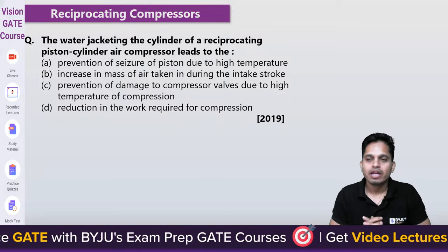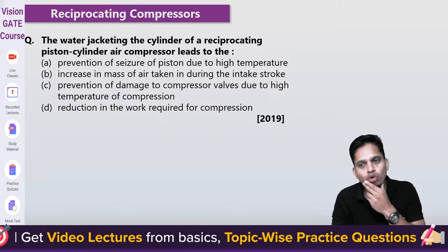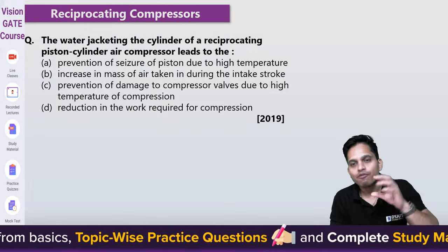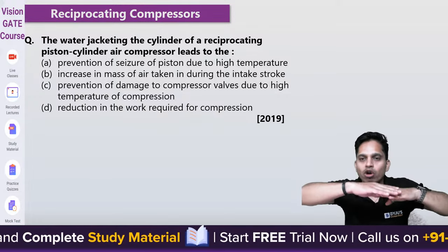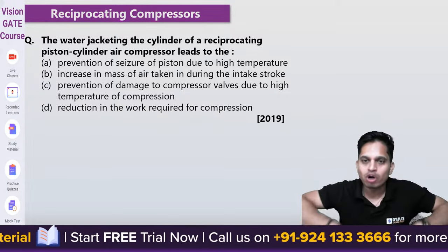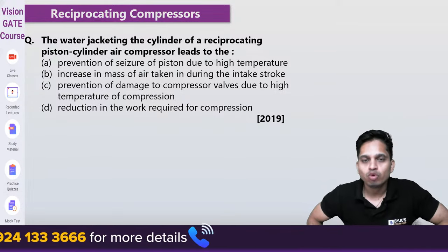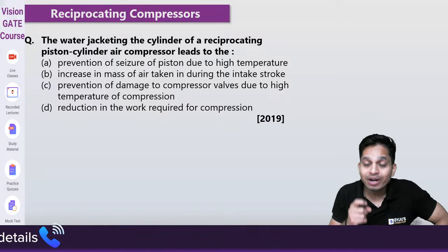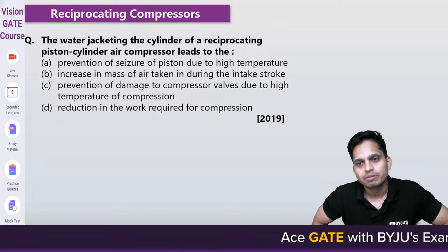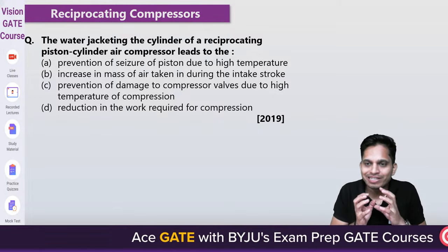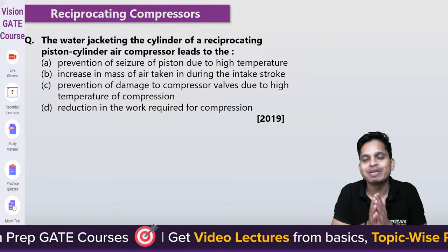No. Usually in a reciprocating compressor, valves are not inside, they are outside. They are plate type valves outside. This is spring controlled, so they will open and close outside only. They will not require space from inside. Then why do you give clearance? You give clearance to accommodate the thermal expansion of the piston. Because if the temperature is really high, the piston can expand because of thermal expansion.